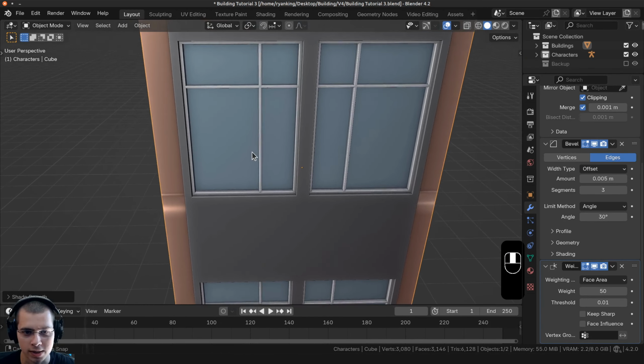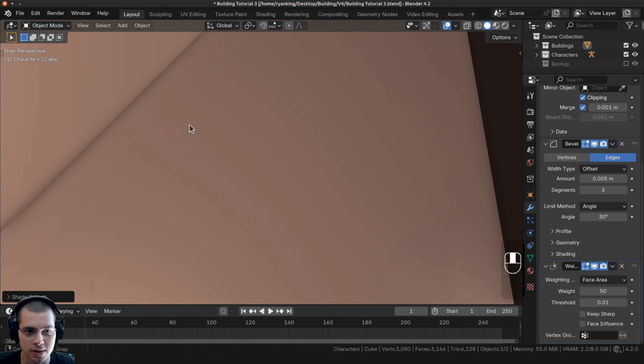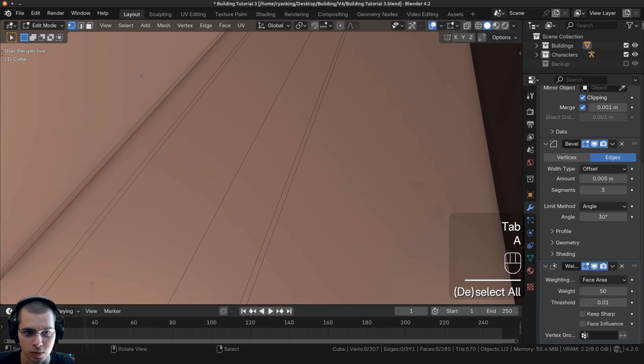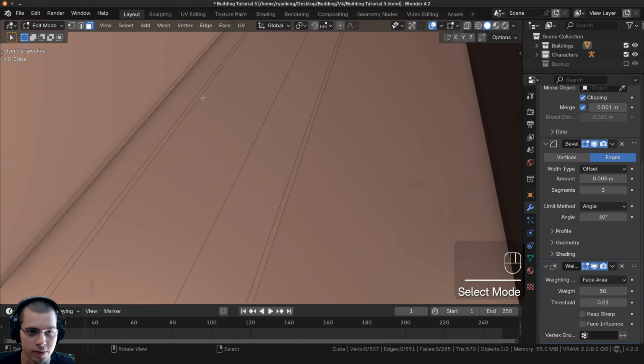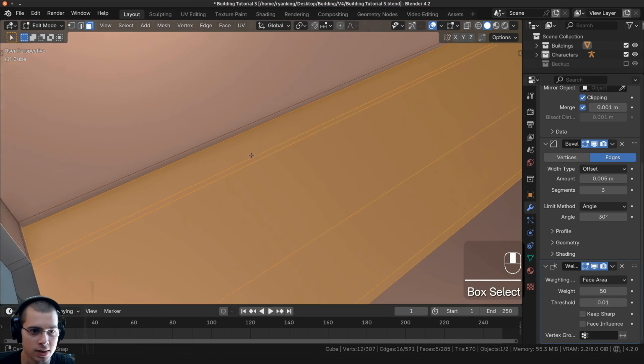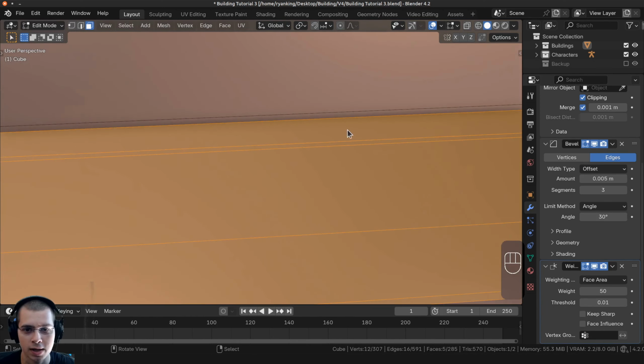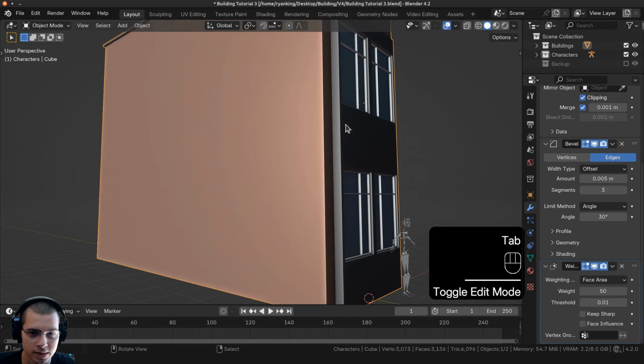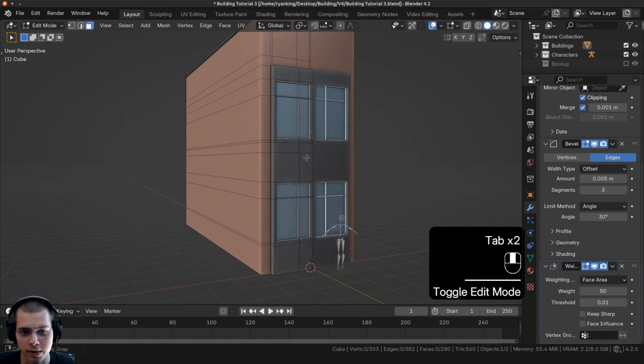Now this might be happening for you where there's this kind of weird glitch right here and shading issues. That is because if we go inside the mesh, you can see there's an extra face in here that we don't need, or there's multiple faces. So we'll go to the face select. We're just going to select those faces in the very middle there. All right, just like that. And then we'll delete those faces. So now you can see those shading issues are fixed there on the outside.